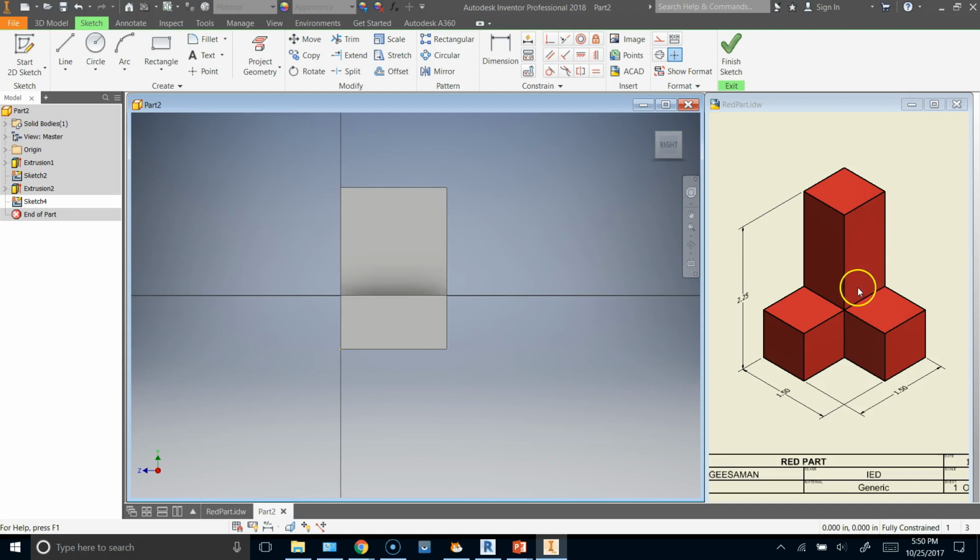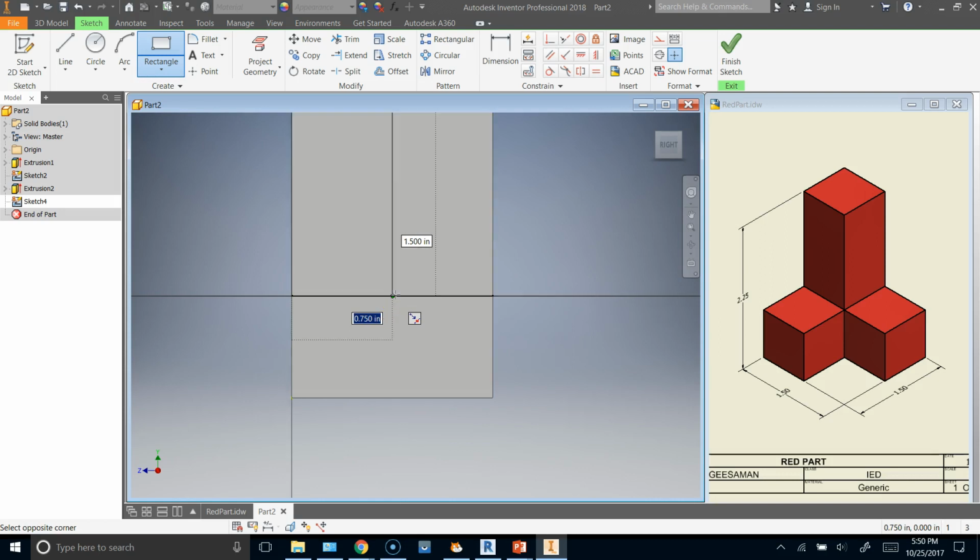And this is the right side view. So I'm going to remove the upper left corner by drawing a rectangle. So I'm going to draw a rectangle that has a vertex in the extreme upper left corner. And down here, because it's 2 blocks deep and I'm removing a 1 block width, I am going to attach to the midpoint, which will be halfway back through the depth. And I can verify that by seeing it says 0.75 inches.